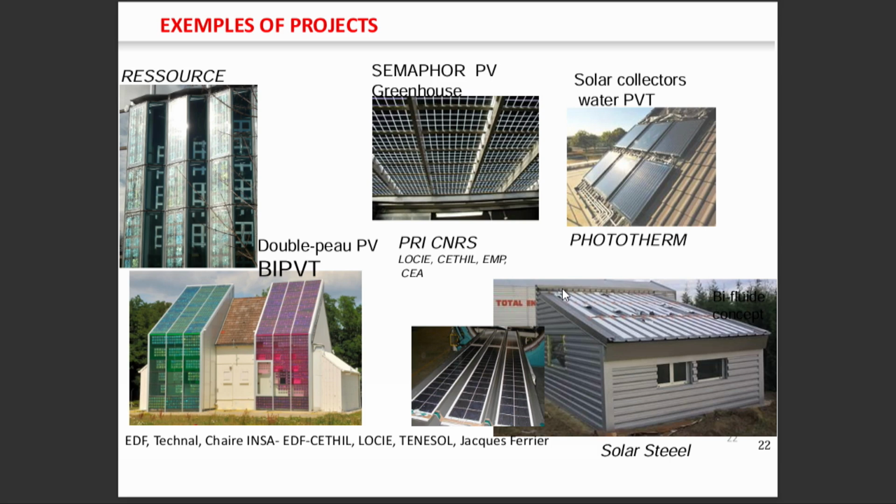So we developed components that give the PV panels a good orientation. Of course, on the other side, it allows the light to cross. You can't put PV panels on both sides because it will not be optimized, and it will create a self-shadow effect.